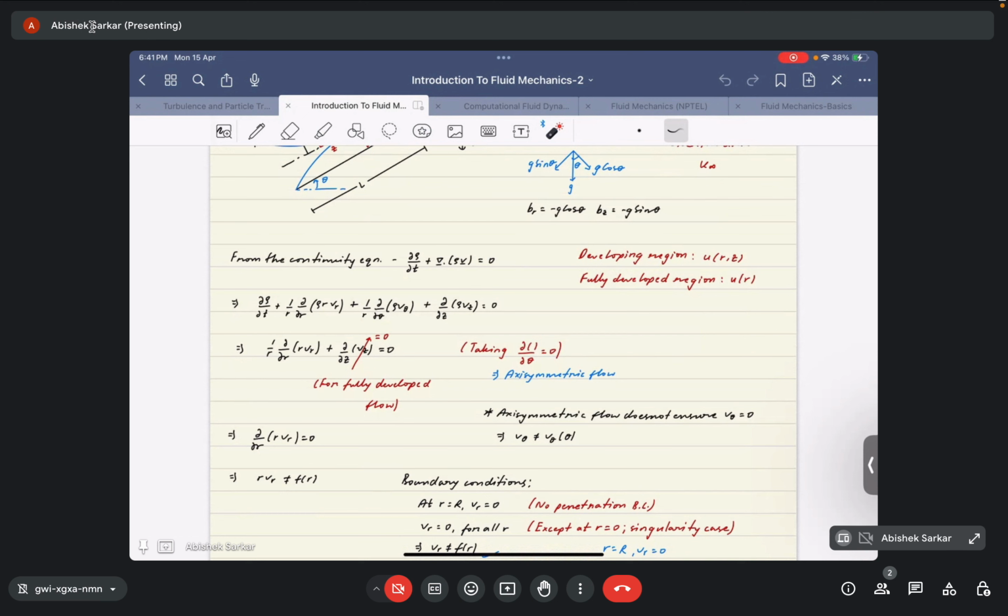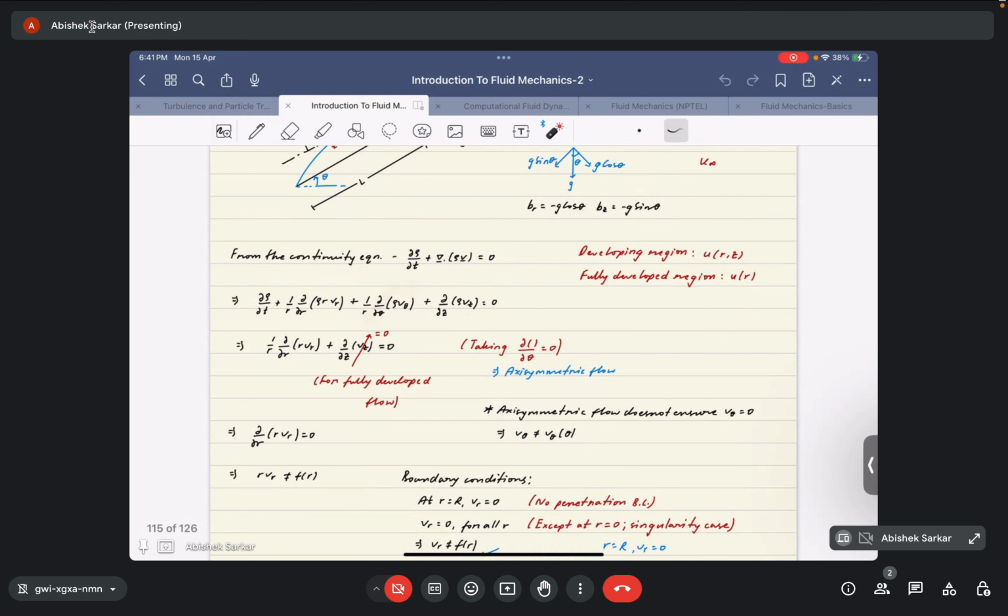First, we take that the flow is axisymmetric. For axisymmetric flows, we have ∂/∂θ = 0. Since ∂/∂θ of any property is 0, this term will go out. We can also consider the flow to be steady, so the time derivative term will also go out. Then we are left with the radial term and the axial term.